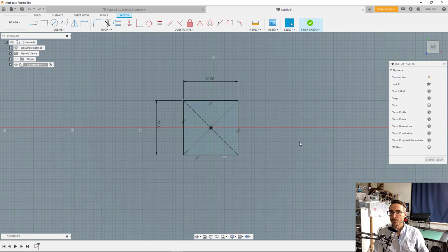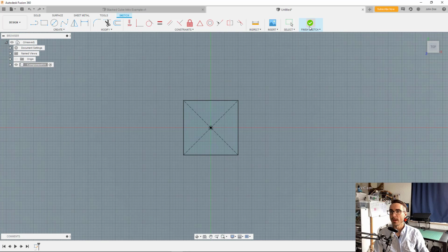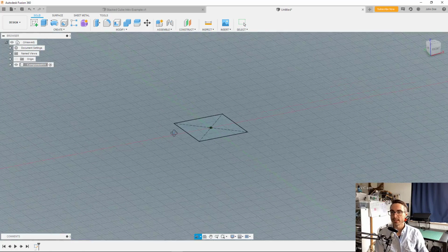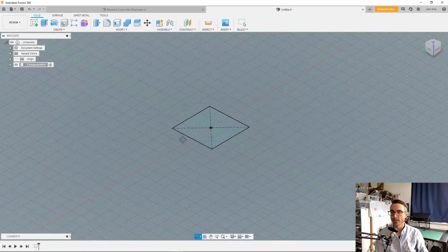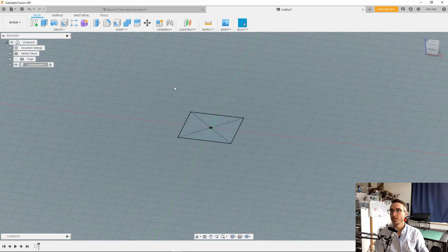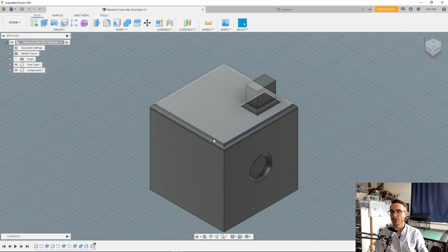The next thing we're going to do is finish this sketch by clicking the right hand tool. When you do that, your menu bar will change up here to objects or options that are more appropriate to three-dimensional views. I could even orbit a little bit to see that we do in fact just have a two-dimensional square drawn on a plane. We're going to do the next step of making this three-dimensional by pulling that base square upwards into space.